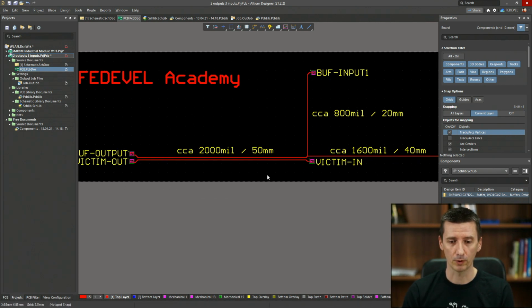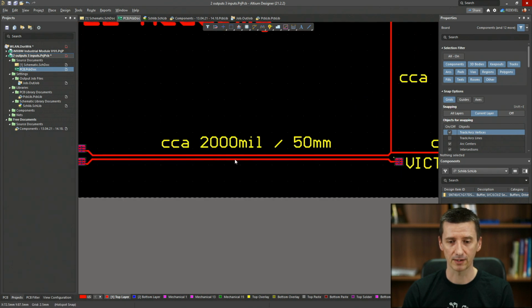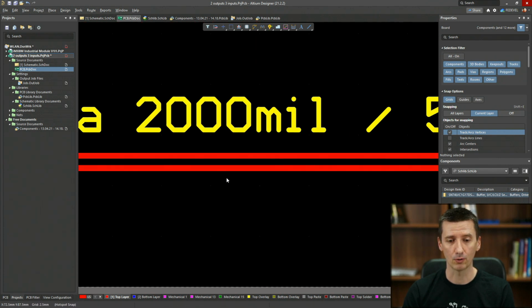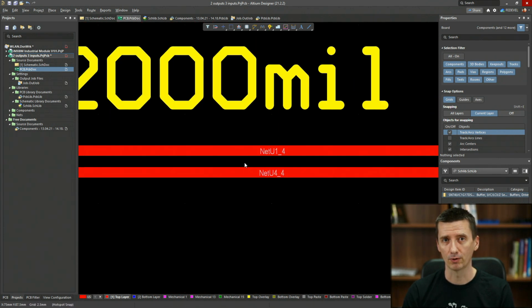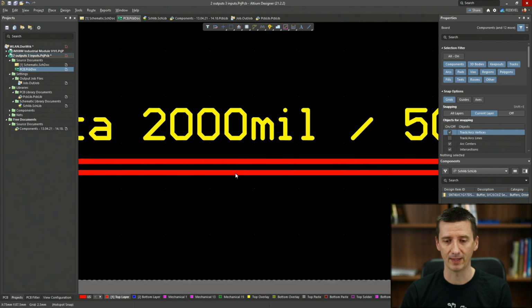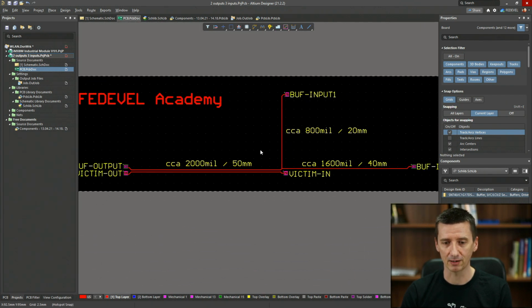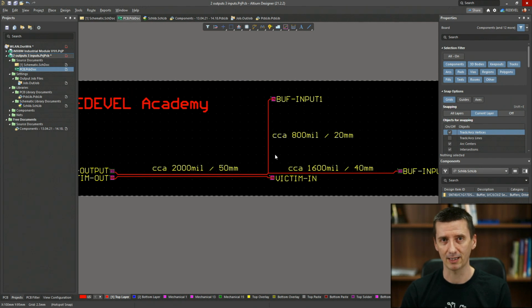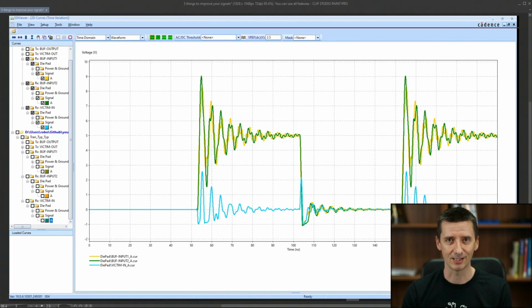And also what we can see here is the place where on your PCB, for example, you need to route signals very close to each other. So here we are going to have a look at how much noise the 10 megahertz signal, which is going to run through this track, how much noise or how much crosstalk it is going to generate on this other signal. And if this simple circuit, if this simple layout is not done properly, then this is what you will get.